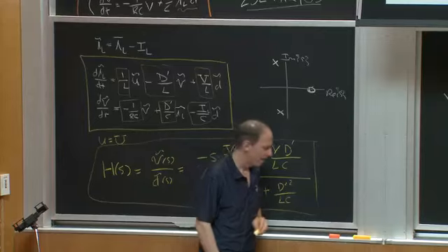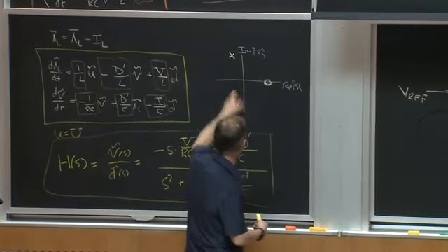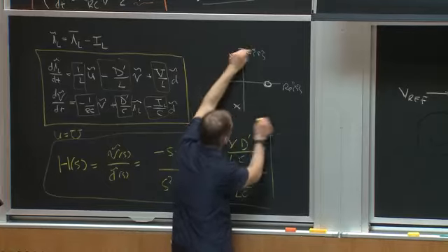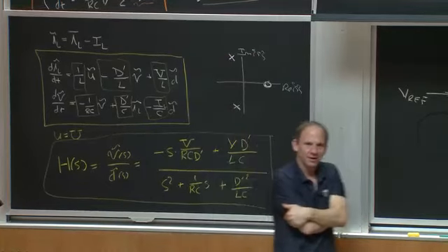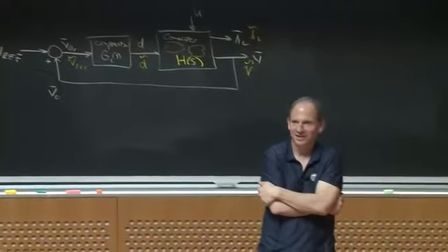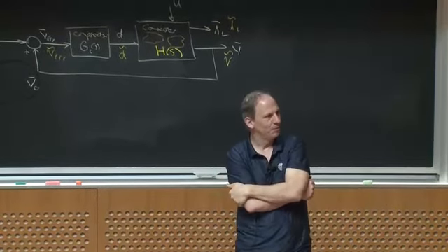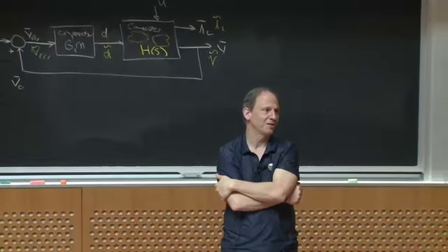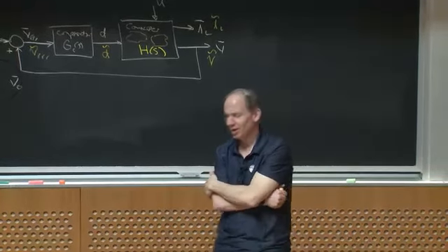Okay? And what that means is if I took this thing and put in a proportional feedback loop, the poles would tend to move towards the 0. Now, if the poles move towards the 0 and the 0 is in the right half plane, that means the thing tends to go unstable. So something with a right half plane 0 is very, very easy to make unstable, generally. Okay? So we don't like that.